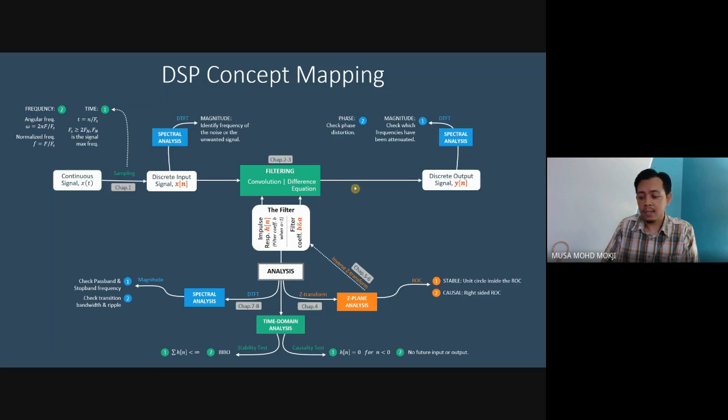Implementation-wise we will do convolution, because you should implement it in the time domain, and that is easier. But for analysis, understanding, manipulation and designing, we use the frequency domain, because the convolution becomes a multiplication.